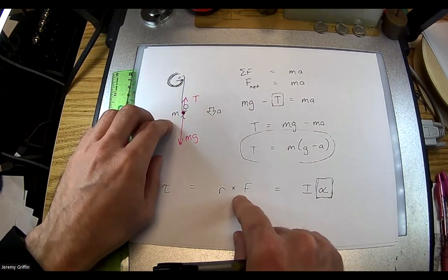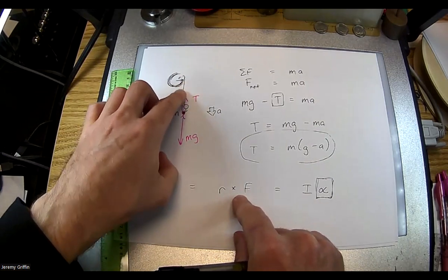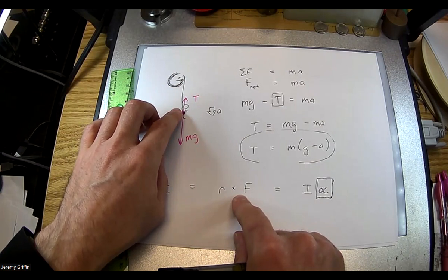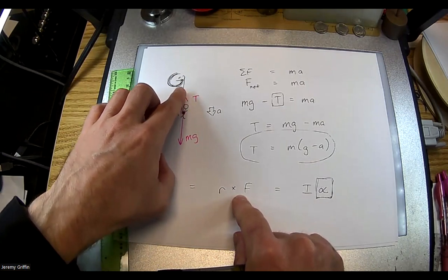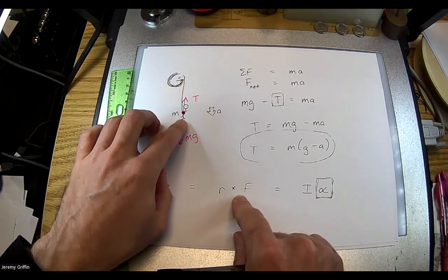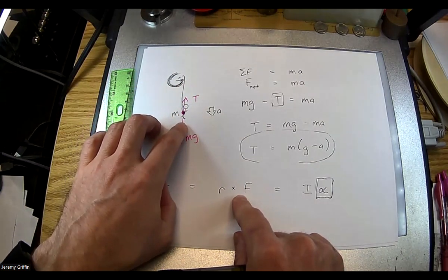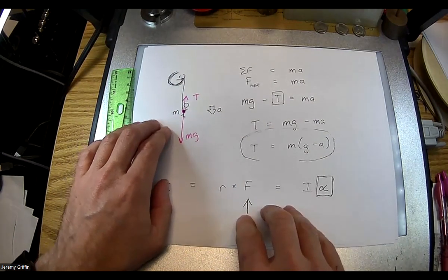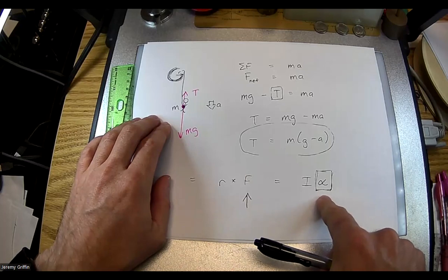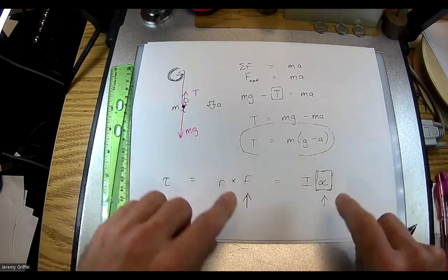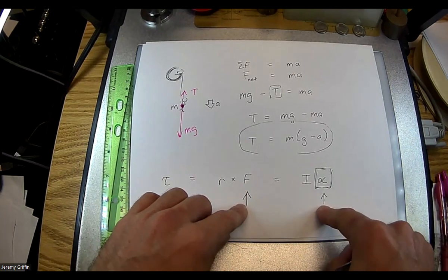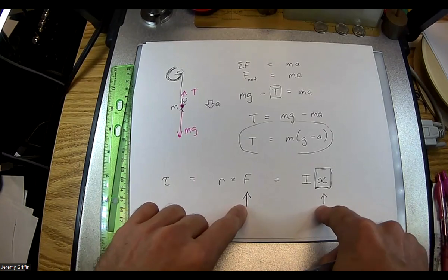Right. Does the force pulling, does the tension change? Does the force pulling down change? How many say it does? Yeah, and it would do what? Guys, as there's more and more rope, this rope gets longer and longer, and it is massive. It has weight. Is that force decreasing or increasing? Increasing. This is going up, right? Now, in isolation, that alone would cause alpha to also do what? Increase. I see a direct relationship. If it's like twice the weight of rope, or like twice the force, you'd be like twice the angular acceleration. But that's not the only thing that changes.